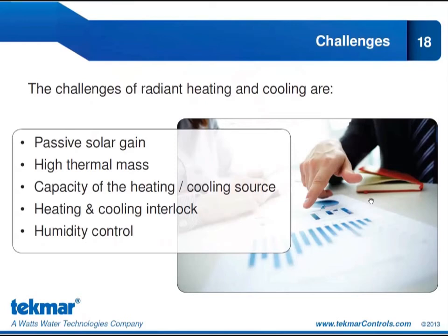We've all heard about bad geothermal designs where we are depleting the ground source energy, so we are taking more energy than we're putting back into the system. That's a design issue that even the best controls can't overcome. The solution to that would be to design appropriately from the start. And we'll talk about that more in this course as well.